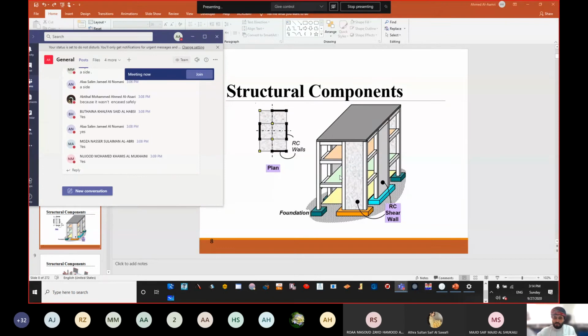So for example, if I bring my phone here, which is acting as an extra weight representing the shear wall. Once again, the shear wall is so heavy, it's so big, so it will make the weight of the structure huge. If we try to apply horizontal load now, you will see that it's hard to move my structure.